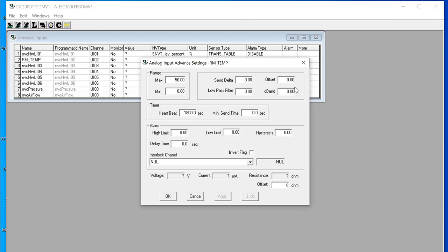Each sensor has a minimum range and a maximum range. These two values you should key in correctly. You check the data sheet for the sensor range. Also for some sensors the range can be configured using a jumper. So based on your setting, you key in the correct value. This is very important. If this is wrong, your sensor reading is all wrong, and your DDC gets the wrong reading.